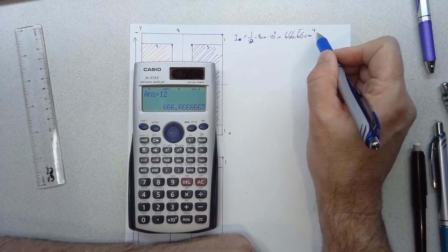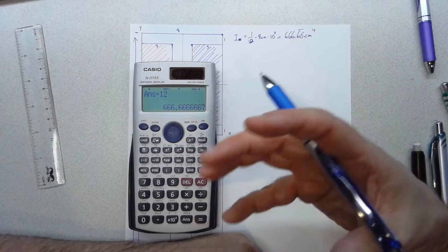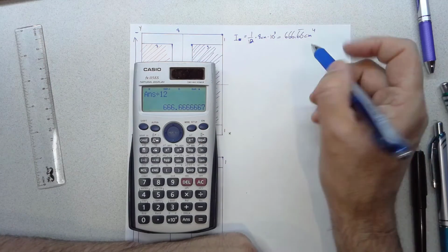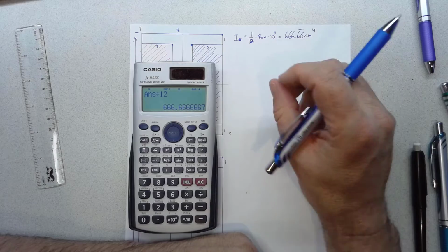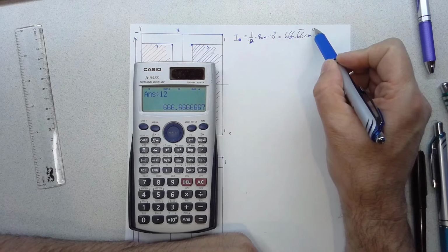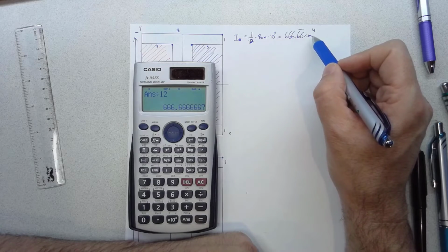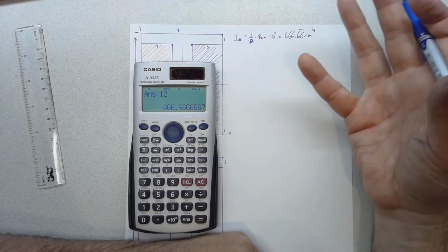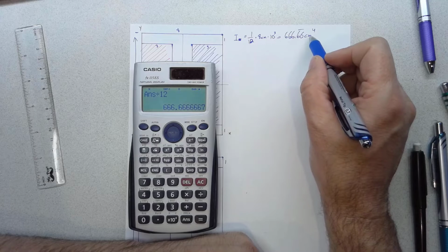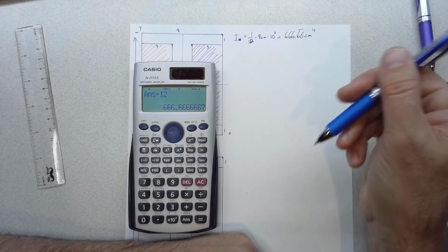And again, centimeters to the 4th doesn't make sense intuitively as a physical property, and we talked about that. The moment of inertia is not a mass, it's not a volume. A centimeter to the first power is a length, centimeters squared is an area, centimeters cubed is a volume. Centimeters to the 4th is not a realistic physical representation, but the units are consistent, so that when we plug them into the moment equation or the shear equation, we do need to keep in mind that the units of I are a length unit to the 4th power, whether that's meters, inches, or feet to the 4th.